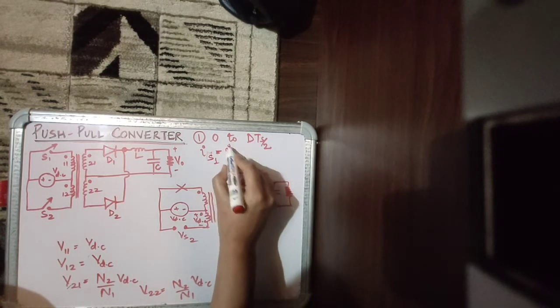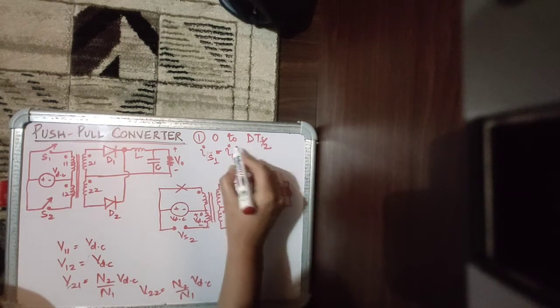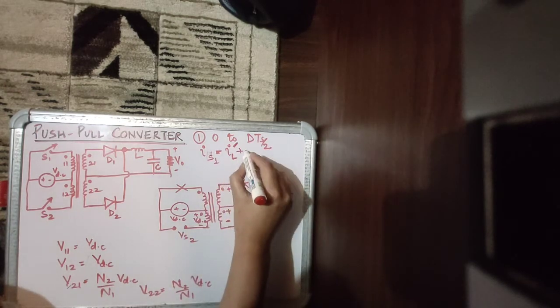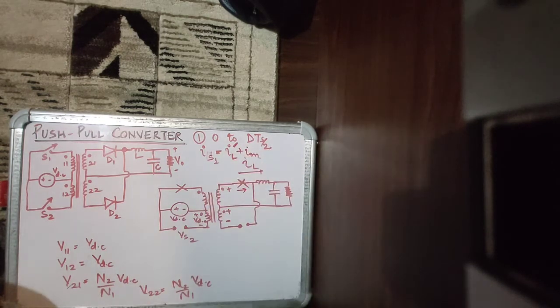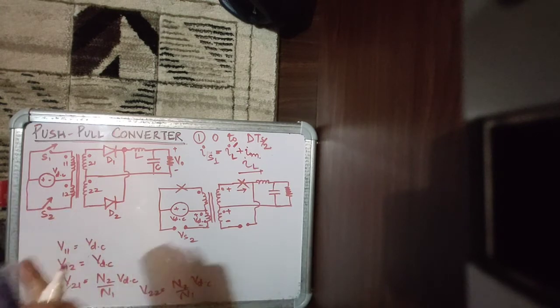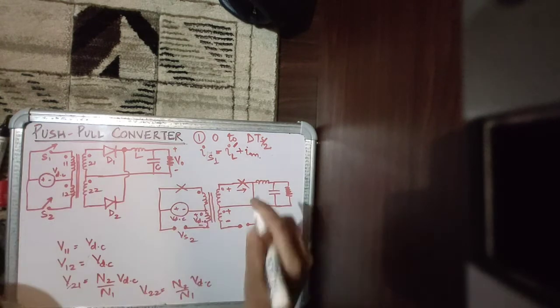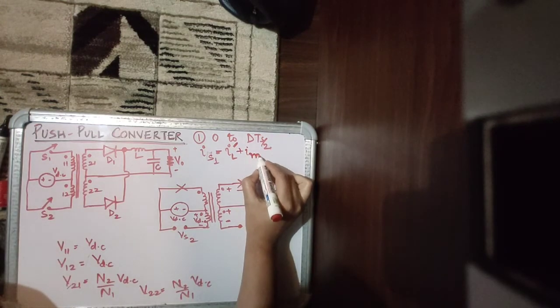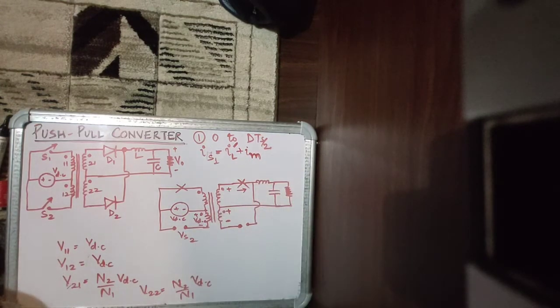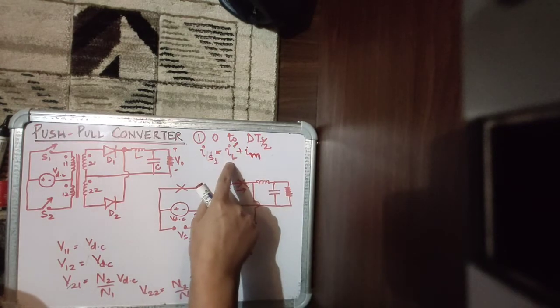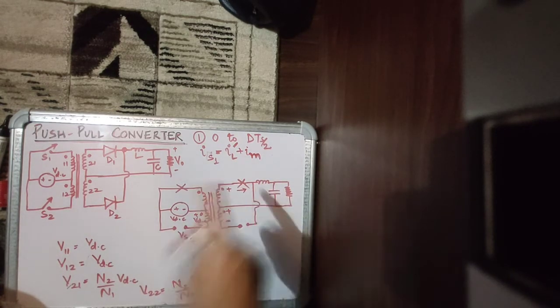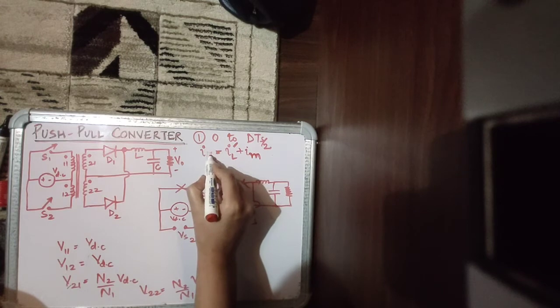It will carry the inductor current, the reflected component of inductor current obviously, and the magnetizing current. Okay, so you have the magnetizing component of current, which will contribute to high power ratings, and because the load component is also flowing on the secondary side, the reflected load component, which is the inductor current in this case, is also flowing.